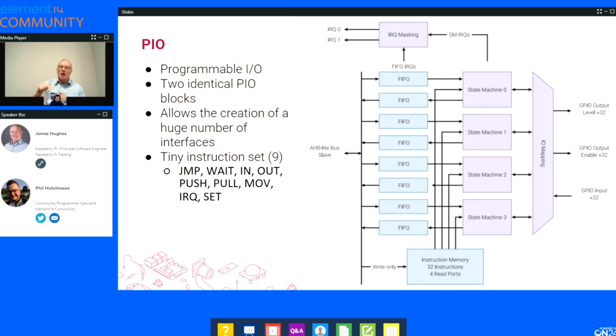But unlike a general purpose processor, they're very, very highly specialized towards I/O, with a very determined focus on determinism, precise timing, and very close integration with the other fixed functions in the hardware. So we make these state machines programmable in a software-like manner.